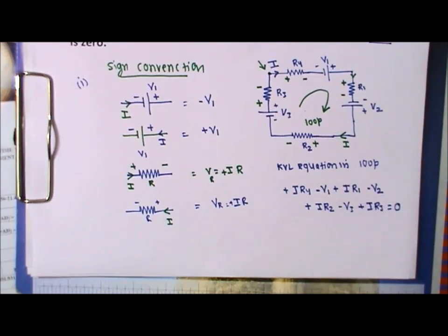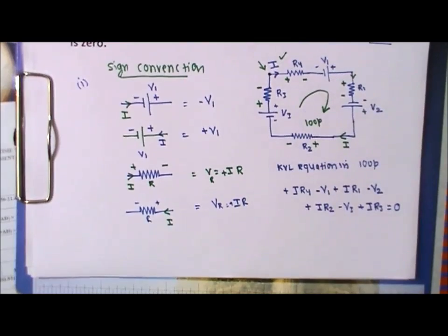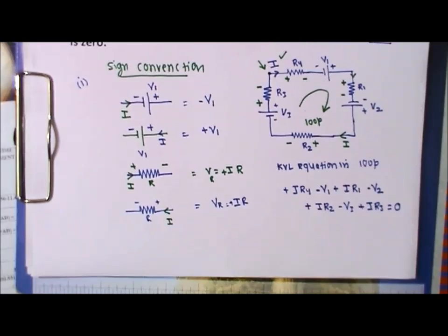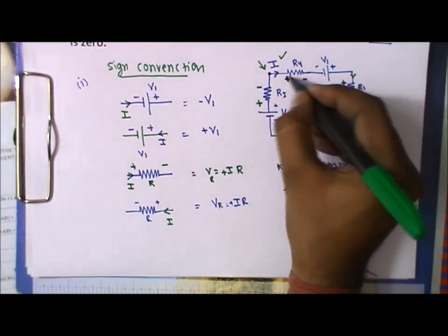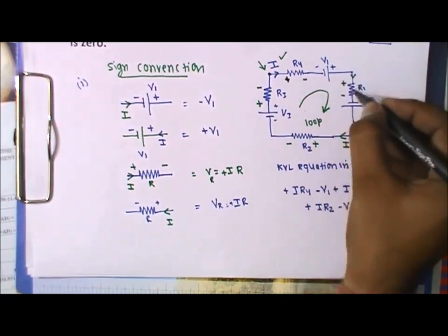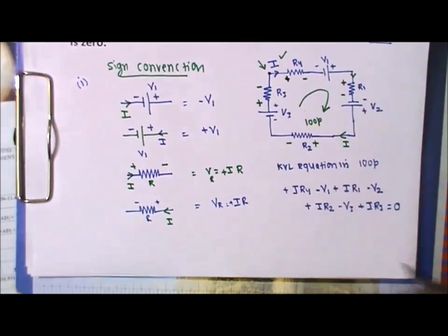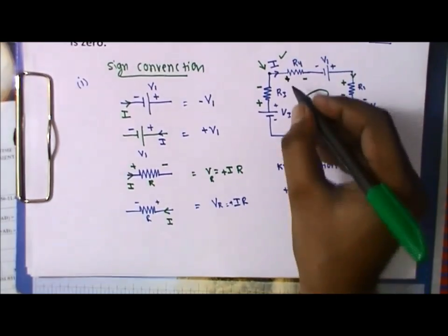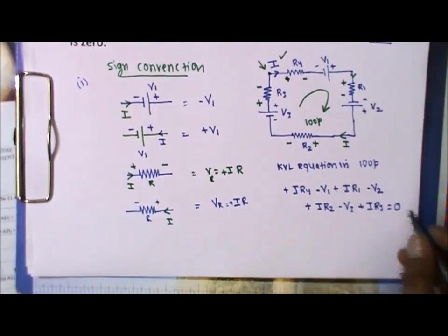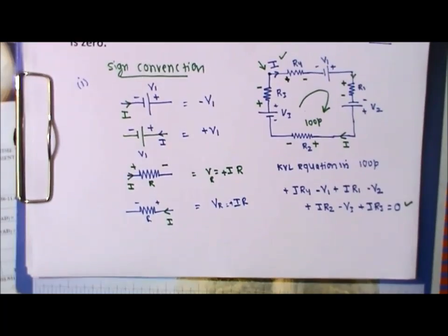So this is the fundamental principle of the KVL, where we observed that firstly we have to assume the direction of the current. This is the first principle. Then we have to put the polarity in the networks like the resistance, inductor and the capacitance. Here in the case of resistance, put the plus minus where the current is entering, plus minus, plus minus, and write the KVL equation assuming the sign which is coming first. So this is the basic general equation of the KVL.